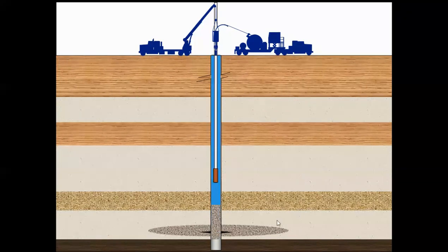Okay, so we'll pump your hydraulic fracturing job into your first zone with the sand slurry, and you might want to keep some sand in the hole because it will act as a plug, so that you can access your second reservoir. If you do not plug this reservoir, because you have hydraulically fractured it, it will obviously have more permeability than your other zones. So if you do not plug it and you pump a fracturing job for the next zone, all the fluid will be taken by this particular zone, which is already fractured, and the other zone will not be fractured. So the plugging or zonal isolation is required for this.